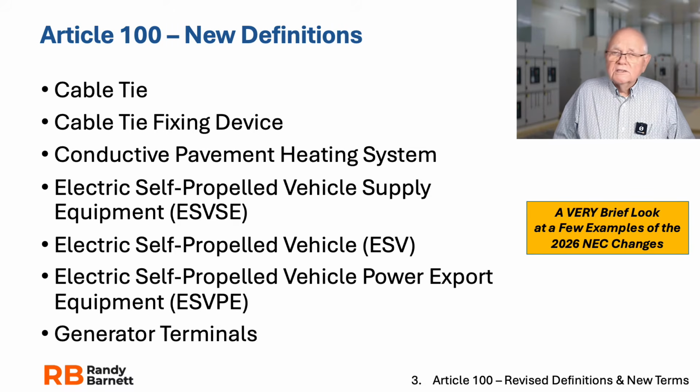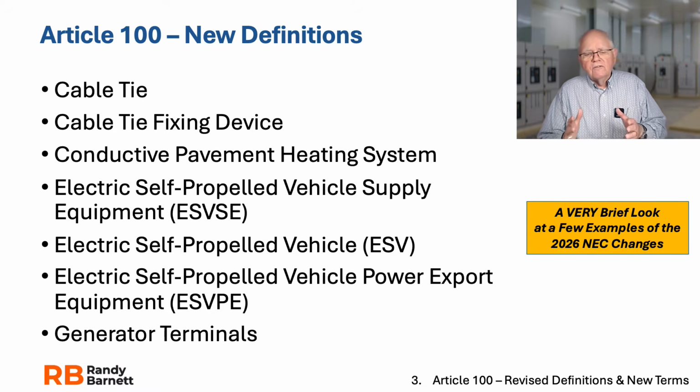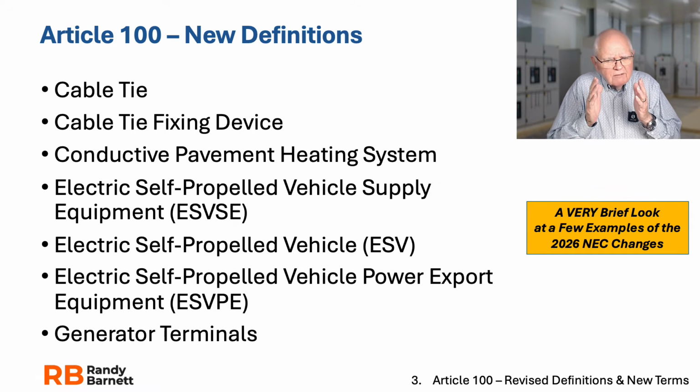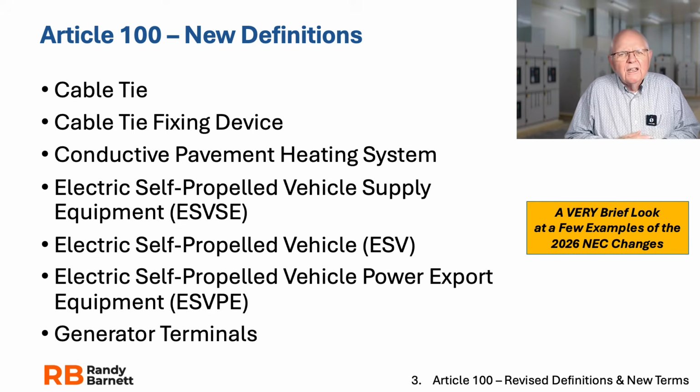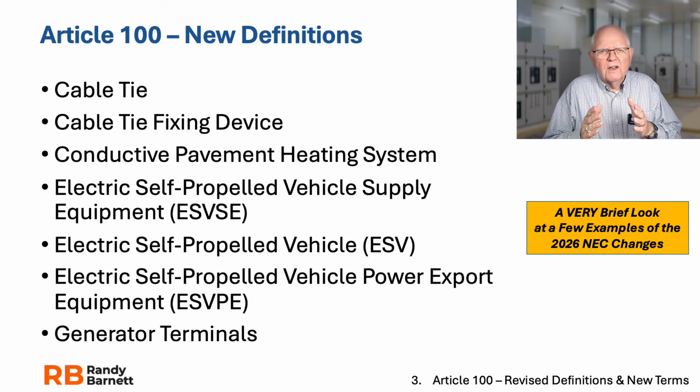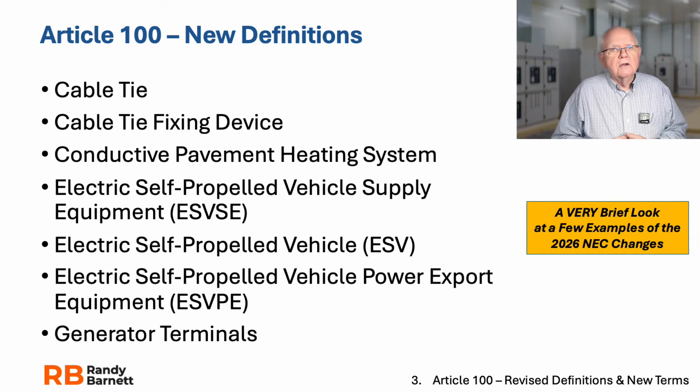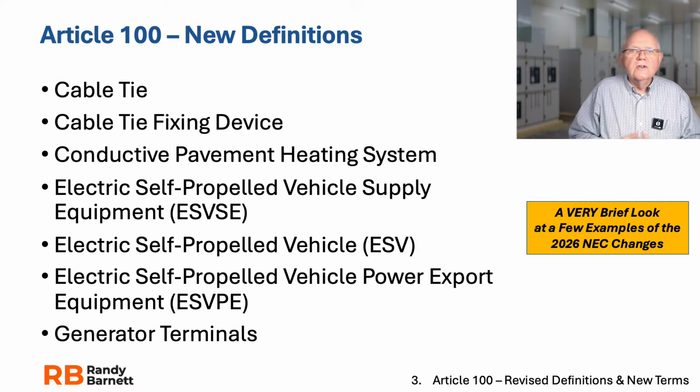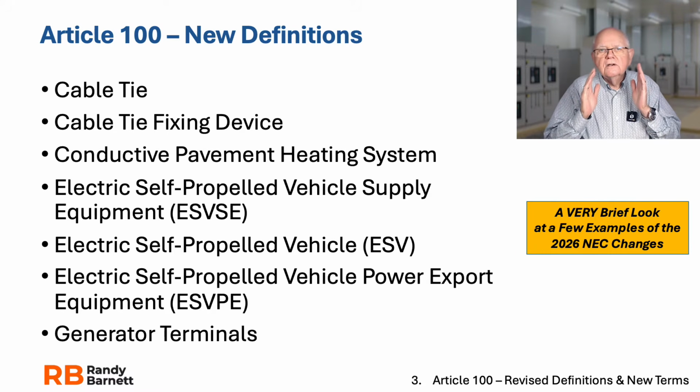But as always, if you really want to know about ground fault circuit interrupters, GFCIs, ask yourself, okay, to use the code book, 2026, it hasn't changed. I need to know something about, what's your question? GFCIs. I got a question on where I need to install a GFCI. Don't just go to 210.8 and expect to find the answer. Go to your index in the back of the book. Look up ground fault circuit interrupters, GFCIs. You'll find a whole list of information. Maybe it's specific for a swimming pool or a fountain or something like that, another location, hazardous locations and all of that. So take a look at your index anytime you have a question you're trying to find information.